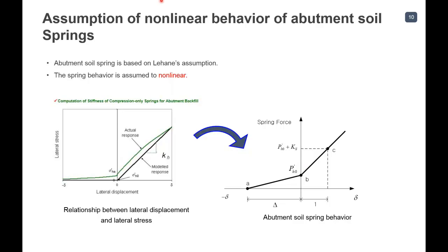Now, the assumption of nonlinear behavior of abutment soil springs. Lehane's assumptions are taken to simulate these nonlinear abutment soil springs. This is how the program will compute the stiffness of the compression only springs for abutment backfill. So you're modeling the abutment backfill with compression only springs. If you model with springs versus the actual response, there is very little difference. So you can actually go for the second approach by using the soil springs.